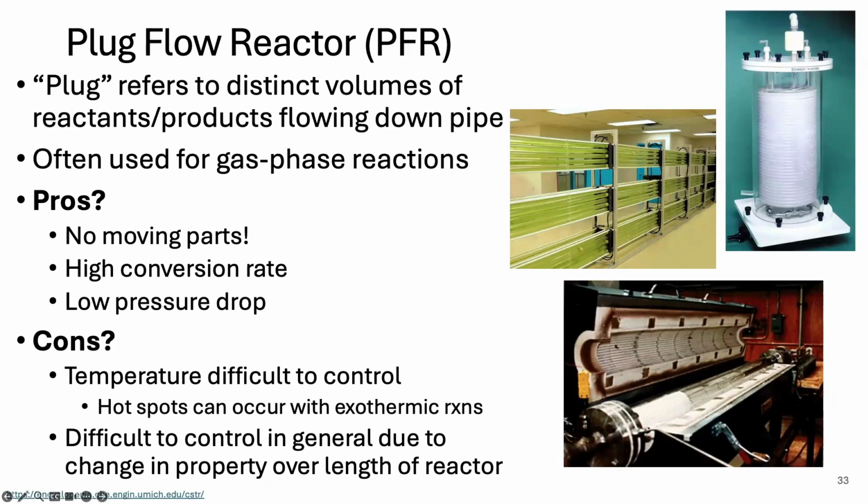Cons, temperature can be difficult to control, so it can be changing as you go down the tube, and so you need proper heat transfer equipment to make sure that you're maintaining, if you want to maintain isothermal conditions throughout.